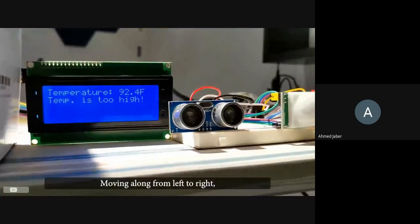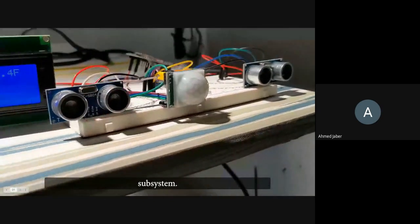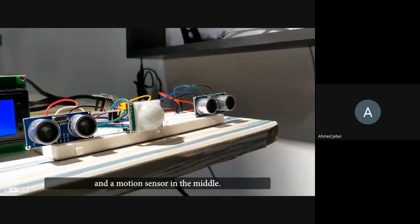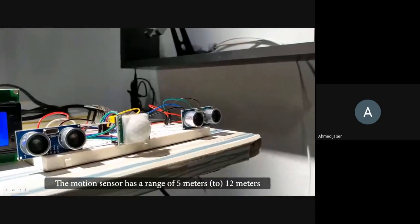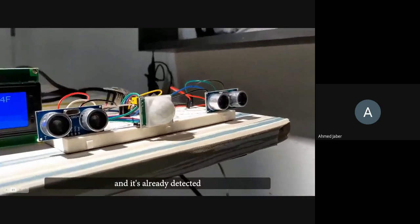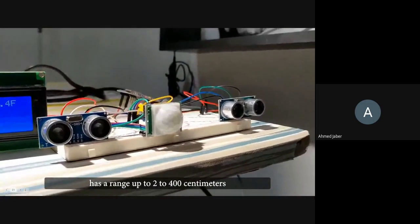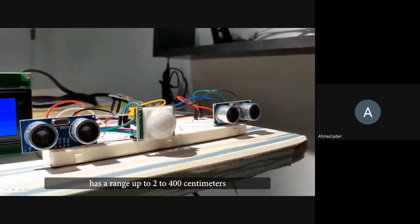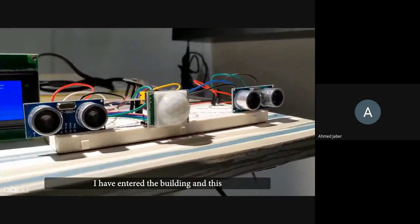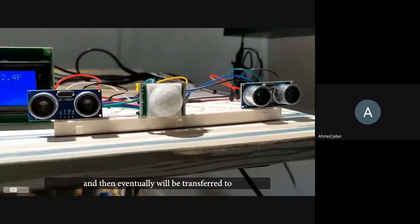Moving along from left to right, as you can see, this is our capacity counter subsystem. Here we have 2 ultrasonic sensors on both sides and a motion sensor in the middle. The motion sensor has a range of 5 to 12 meters, and it's already detected my movement. And the ultrasonic sensors have a range of 2 to 400 centimeters. Based on the algorithm, since I moved from left to right, I have entered the building, and this data is also going to the Google Sheet, and then eventually will be transferred to the website.